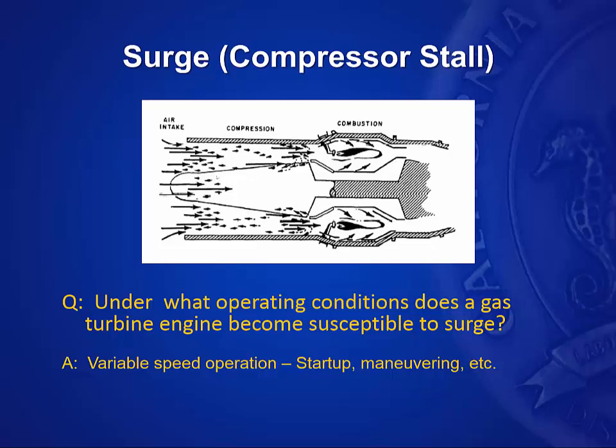And when we're talking compressor stall, primarily it has to do with the velocity of the air going through the engine, and because of the changes in velocity of the turbine blades themselves, the angle of attack at which air is hitting the leading edge of that compressor blade. So if we can adjust for angle of attack, we can minimize or significantly reduce these effects of stall.